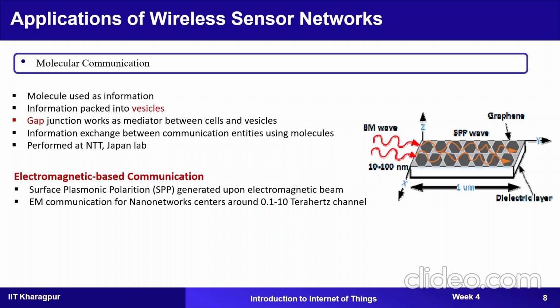There is a relationship between transmission range and sensing range. Sensing range is the distance up to which your sensor is going to sense the region. However, transmission range is the distance up to which it can transmit the data. Basically it can be shown with the help of a circular region. The circular region up to which your sensor can sense the area is the sensing range, while the point up to which your sensor can transmit the data is the transmission range.